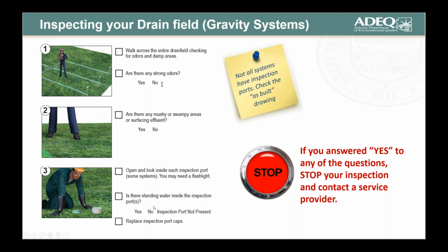And so that's going to indicate, of course, how well the percolation is going in there. Now if there's any standing water at all, yes, well then, we call in a service tech. I don't see that that's necessarily a failed system just because there is some standing water. And then, of course, be sure to replace your inspection port caps.